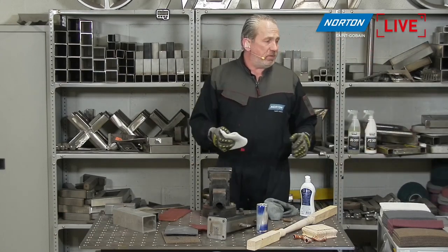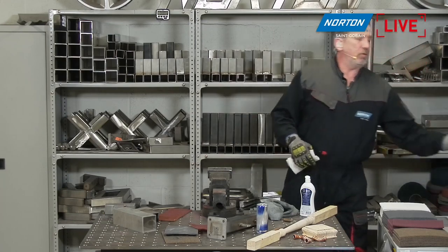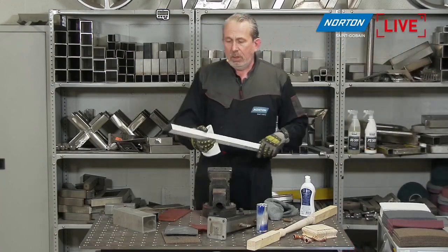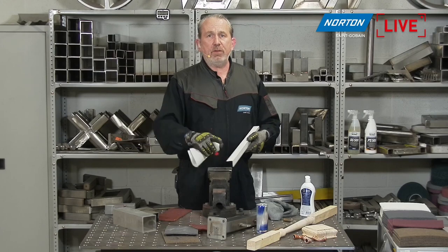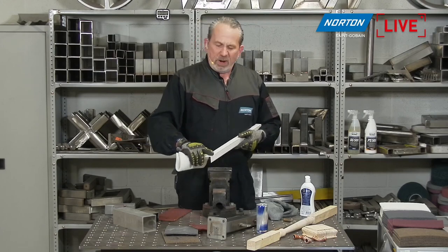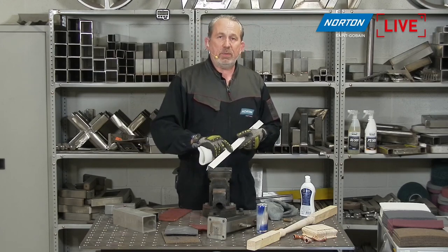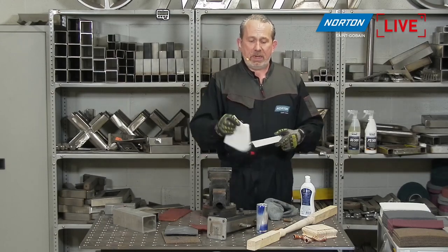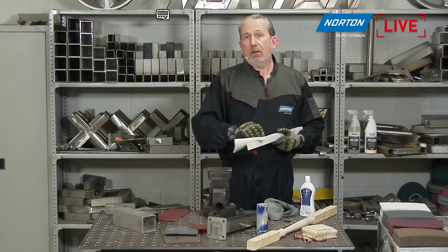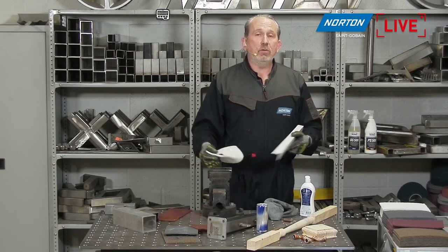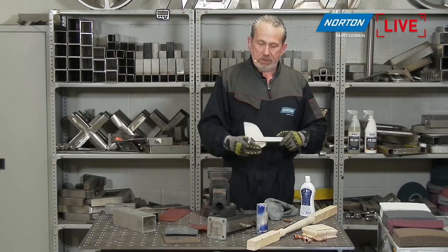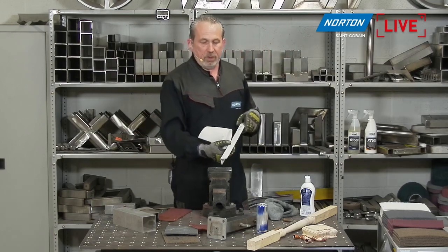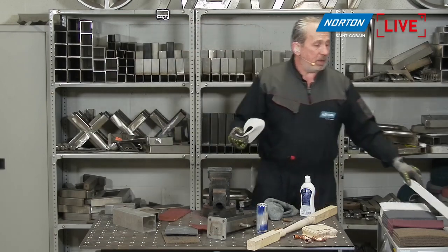Another one is UPVC. Most of us have got UPVC windows these days. So a little piece like this, if UPVC started to go dull or brown or a bit dark looking because of years of being in service, again, some cleaning fluid, the white hand pad. Take this to your UPVC and it'll look like your windows have been installed the day before. It's really that good. It makes a really nice finish of a product like this.